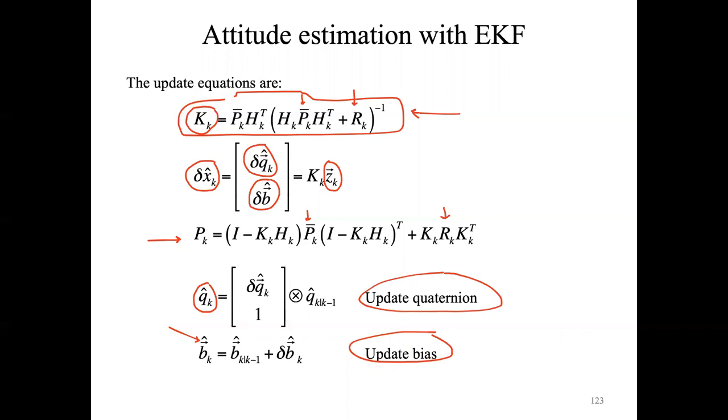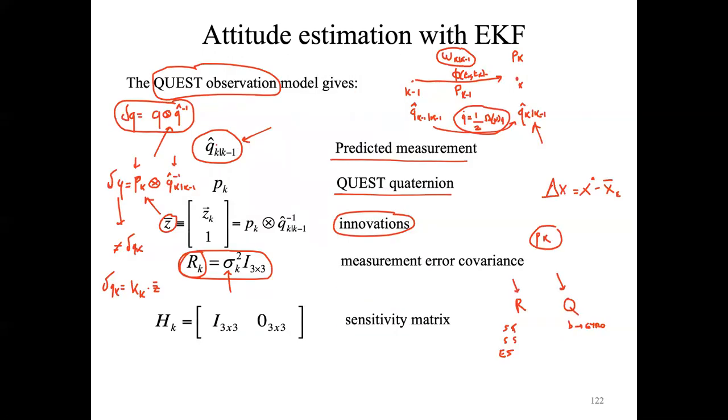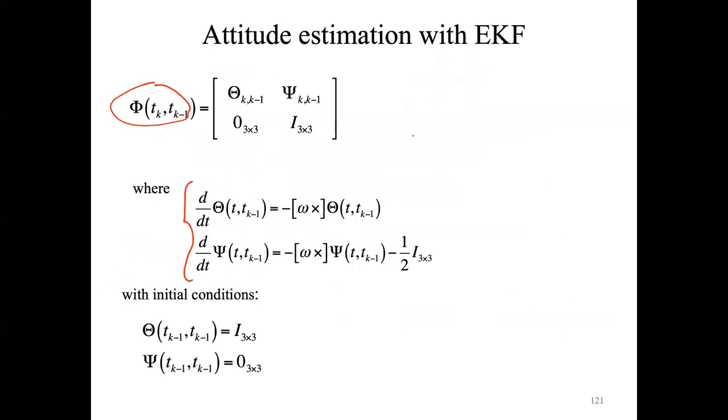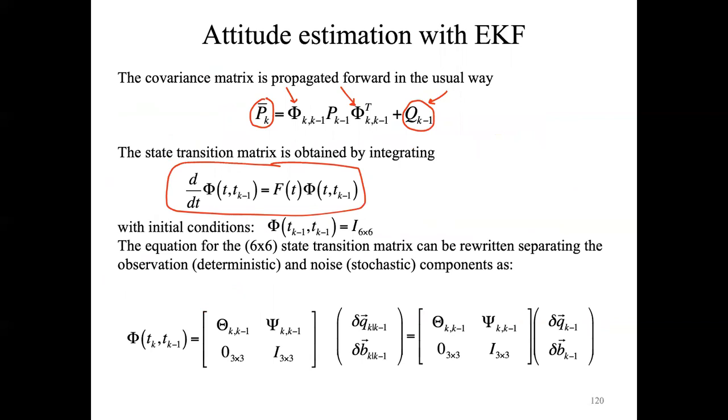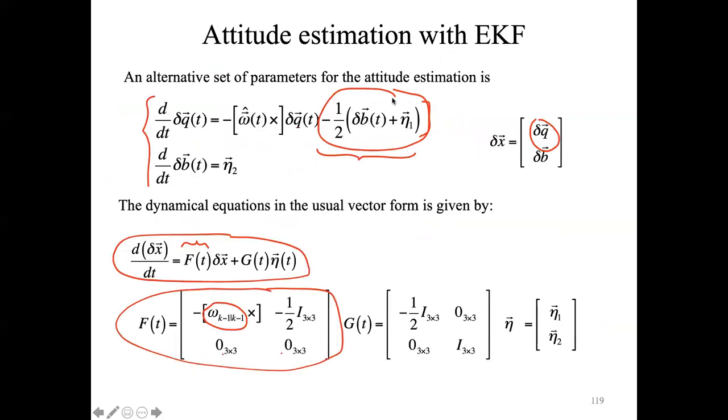The other question was regarding the assumption that we have made to implement the Kalman filter in this way. The main assumption is indeed by using the Farrenkopf model of the gyroscope. So the bias itself varies over time with the Gaussian noise, eta 2. And also we have a direct Gaussian noise in the readout of the gyroscope, when we want to determine directly omega of the gyroscope.